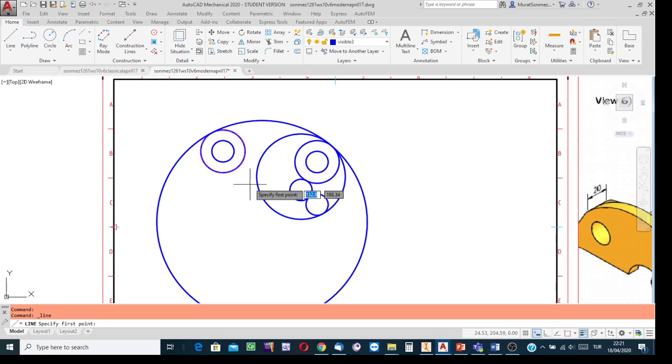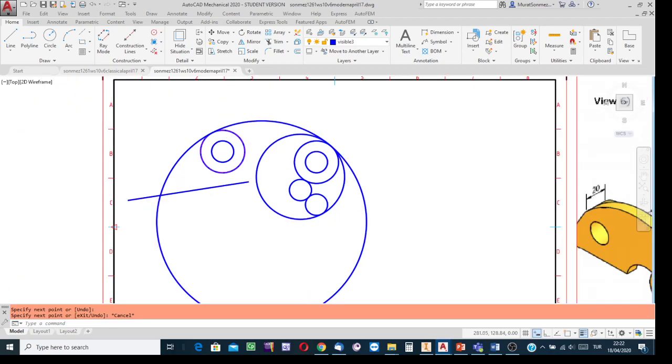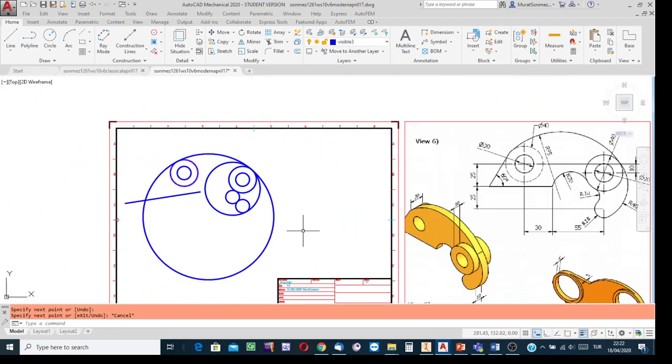Now my cursor is ready to make a click to indicate the starting point of the line, the end point of the line. It is at lower level and at the right hand side. So click and then create the line. I don't know the length of that line. To be safe, I created it extended further. Although I know that it is a horizontal line, at the creation stage I created it as if inclined. Okay. Press the escape button and then the rest. Input the constraint.